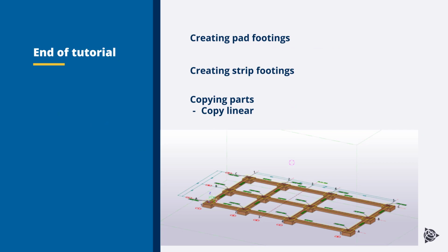You have now reached the end of this tutorial. In this tutorial, you've learned how to create foundations for a model, how to create pad footings and strip footings, and how to copy existing parts to speed up the creation process.